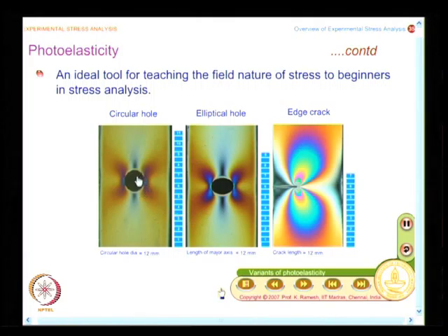You see very few fringes here, you see slightly more number of fringes here, and I have not put that as 6, I put that as 7. When I put it at 6, you have a large number of fringes here. So, if you have an appreciation of looking at fringe information, the density indirectly indicates the stress levels are high.